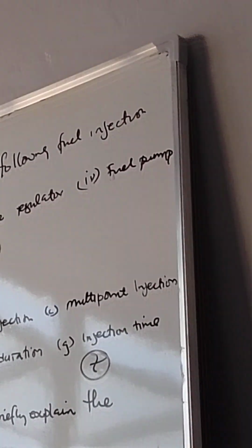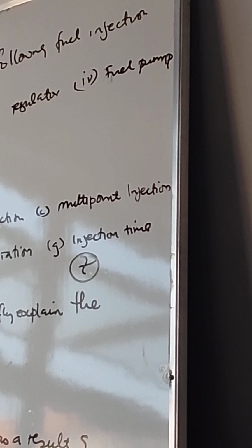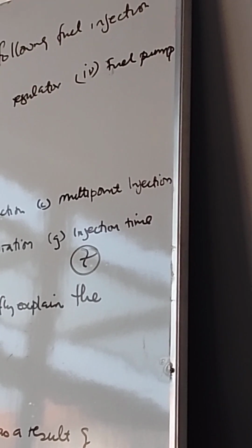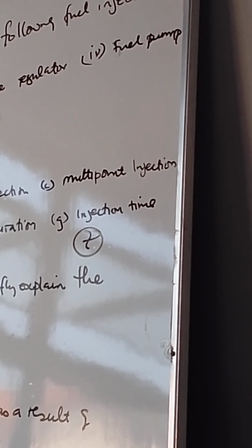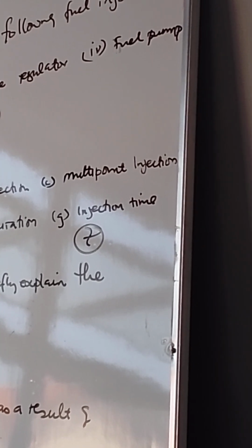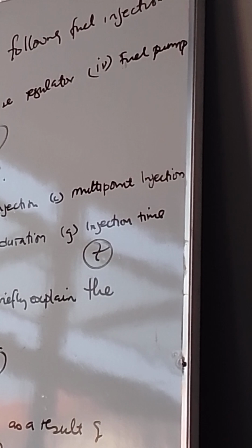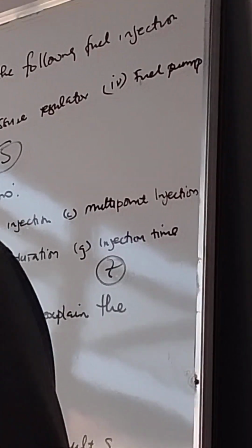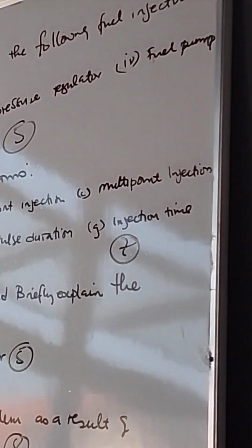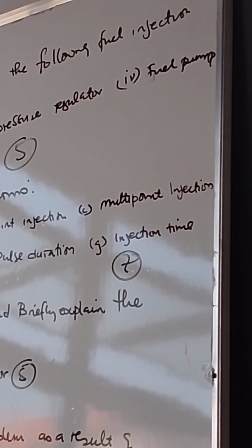Both windings start at the same point but terminate at two different points: the pulling winding at the motor terminal, the holding winding at the housing. So when testing, we want to confirm that.